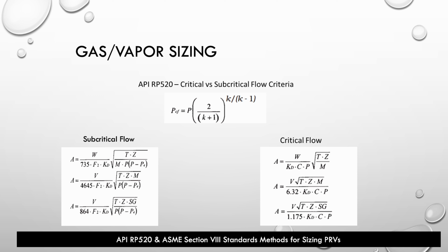So, like we have mentioned earlier, the only difference is that this time you're going to need to consult the API code called API RP 520 for what critical and what subcritical means. Right. So before, we knew it's a more general term, with more flexibility around it. There are codes assigned for it, but in our case, they have to completely regulate what that means. Because again, it's an HSE issue.